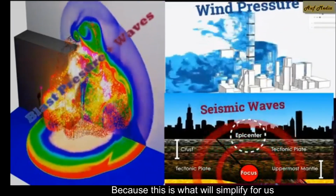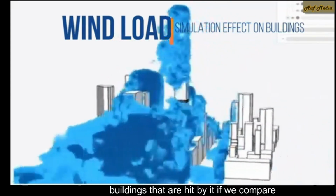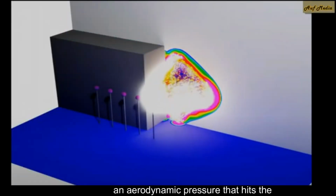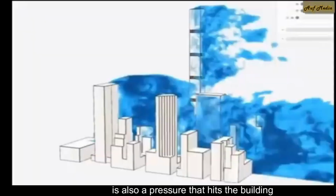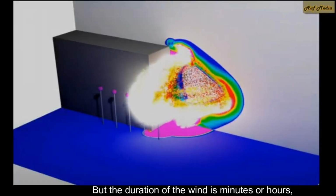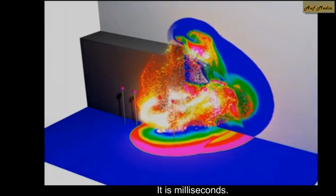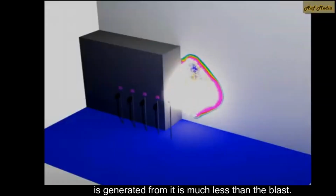Because this is what will simplify for us the concept of how the blast load affects the buildings that are hit by it. If we compare it with the wind, they are both pressures. The wind is an aerodynamic pressure that hits the building and exits. The blast is also a pressure that hits the building and affects it. But the duration of the wind is minutes or hours, while the duration of the blast is milliseconds. It does not complete a second. Therefore, the wind load, the pressure generated from it, is much less than the blast.